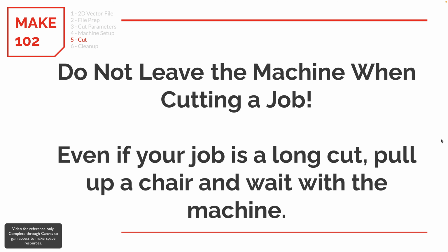And the biggest thing is, do not leave the laser cutter. You must stay with the laser cutter. Even if you have a 50-minute engraving job, you cannot walk away from the laser cutter. You must stay there. If you know the job is going to be long, bring your laptop, roll a table over next to the laser cutter and work right next to it. But we do not want to see you going to the bathroom, leaving the makerspace, or walking away from the laser while the laser is running. This is a big no-no. You may not walk away from the laser while your job is running.